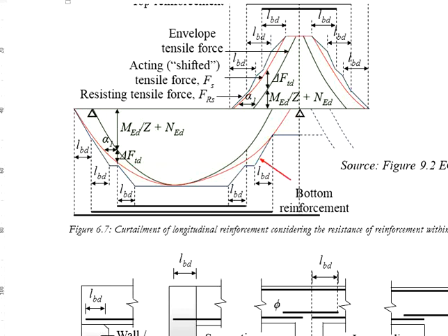If the angle here is smaller than this, that means if you start here, there is a risk that certain areas will have resistance less than what is required. In this case, you might need to offset a bit in order to make sure the area here representing the resistance is always greater than what is required. Then you will do the same for the third group of the reinforcement.